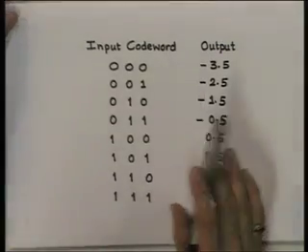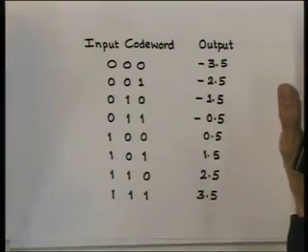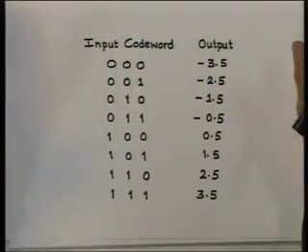So, construction of the intervals, their location, etc., can be viewed as part of the design of an encoder. Selection of reconstruction values is part of the design of a decoder. However, the fidelity or accuracy of the reconstruction depends on both the intervals and the reconstruction values. We call this encoder decoder pair a quantizer.